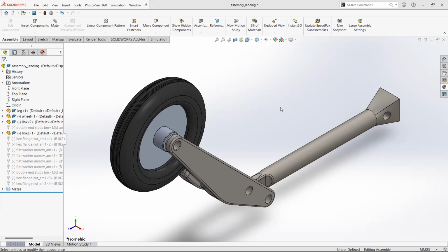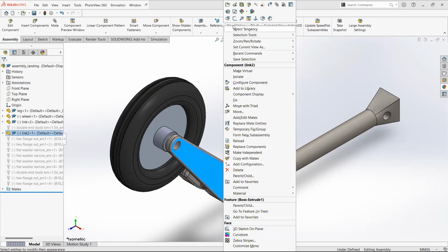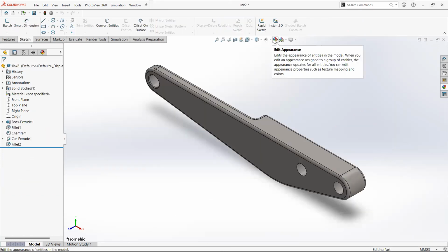So first of all, in the last class, when we created this assembly, I already created the different parts and we just created the assembly. But as you might have noticed, the parts in my assembly in here are colored. And this was done via the appearance tab in here. This can be done in the assembly level, like in this mode, or if we right click on a part, we can open the part, and from here we can also edit appearance.